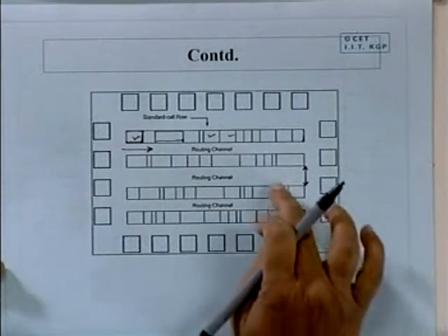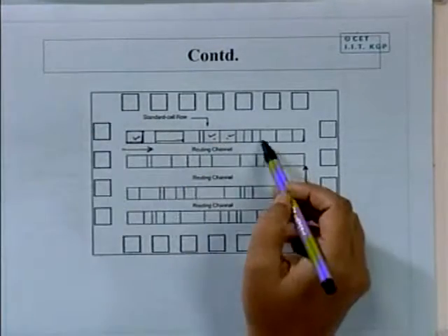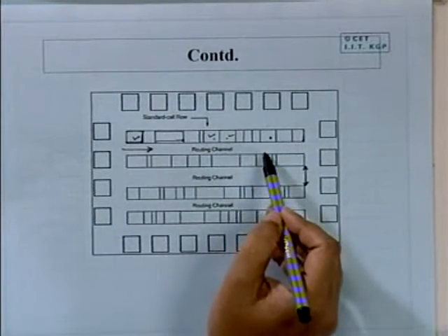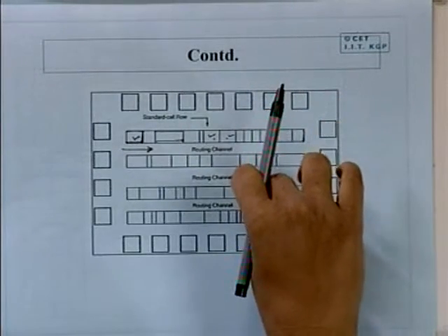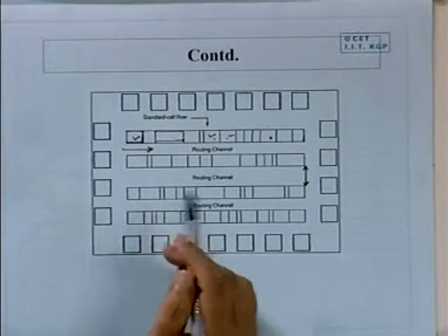So now it is the designer's task, because all the cells are available, these are ready-made cells, they are taking them from the libraries, only selecting these routing channels, what will be the height of the channel, what will be the connections. And it is done nowadays by some CAD tools, not by the designer. We are discussing the floor plan, placement, routing, which are back end design, meaning the physical design automation.